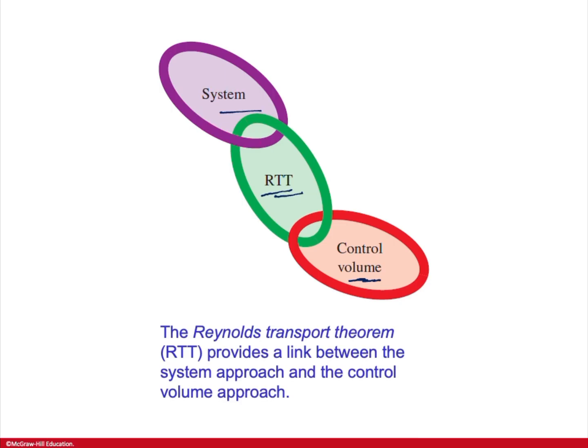So that's part of the reason. If you want the equivalent form of these conservation laws for a fluid system, where it is more convenient to look at the Eulerian form of description or control volume form of description, you need to convert these conservation laws into those descriptions. So you use this Reynolds transport theorem or material derivative concepts to make that conversion on the fly. So that's the reason we are doing it. If you have a good understanding of how the Reynolds transport theorem works, you can easily derive the mass conservation law, momentum conservation law, and energy conservation law by just literally substituting the variables.